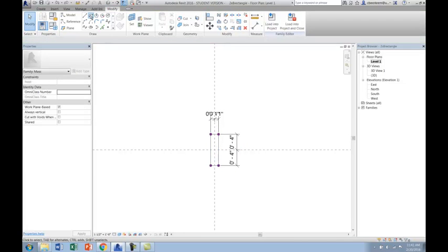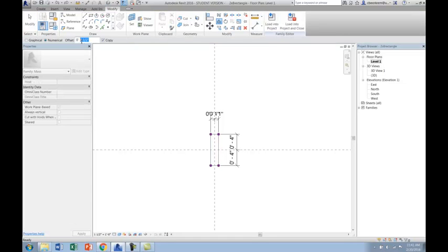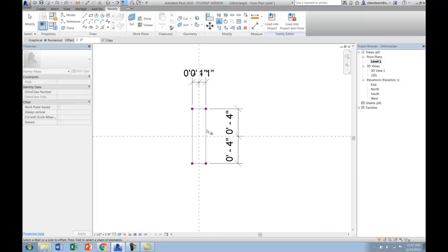Actually, I think the easiest way to do this might be to start offsetting the lines that we've got so that we stay on center here. So if I'm going to use this not as a mullion but as a structural member, say in a diagrid representation, and again, we'll look at a couple of different ways to do diagrids like this. This is the simplest one to quickly start doing it. I'm going to go ahead and offset these lines 12 inches.